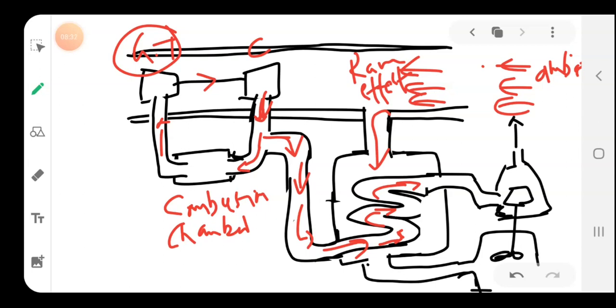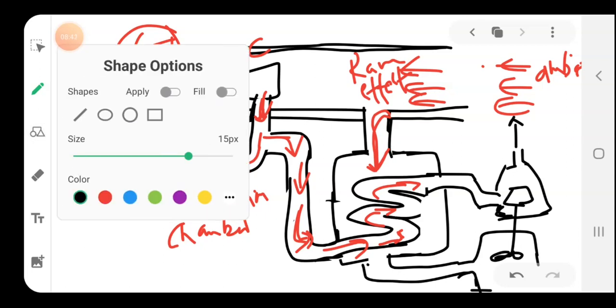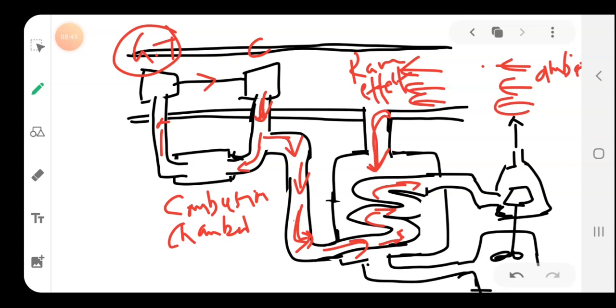since the temperature of this compressed air is higher than the temperature of this air, okay, I'll show you. This air will be somewhat cooler than this red colored air, because it is not compressed. So this cooler air will absorb heat from here. So this air will be cooled, and cooled even again when it is passed through the cooling turbine.